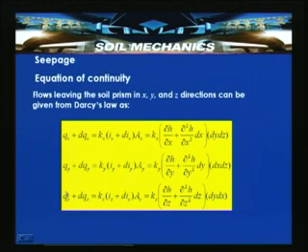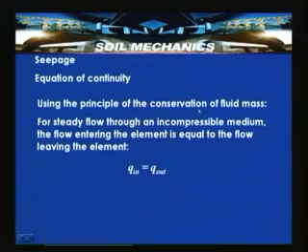So, by using Darcy's law, we have the flows entering and leaving the element. Now, using the principle of conservation of mass, let us derive the equation of continuity. Using the principle of conservation of fluid mass, for steady flow through an incompressible medium, the assumption is that the medium is incompressible.